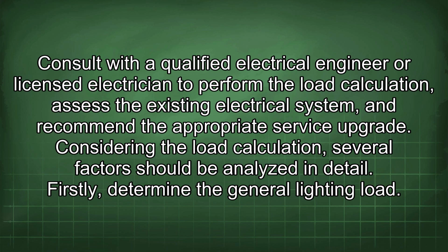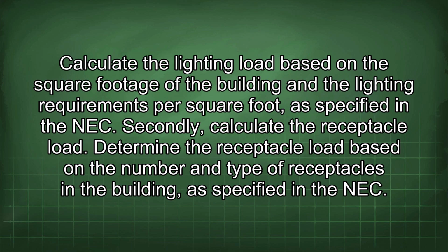Considering the load calculation, several factors should be analyzed in detail. Firstly, determine the general lighting load. Calculate the lighting load based on the square footage of the building and the lighting requirements per square foot, as specified in the NEC. Secondly, calculate the receptacle load.